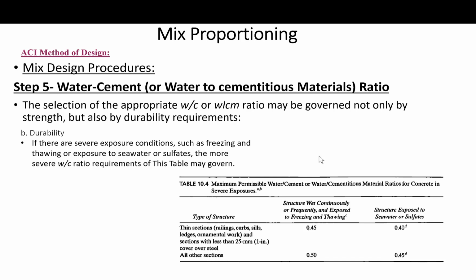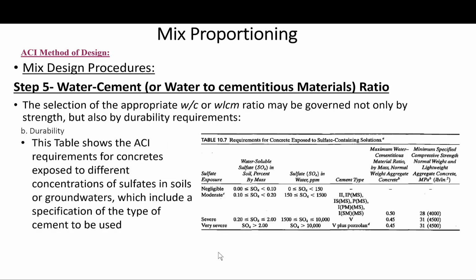Maybe, for example, the Canadian standards will also call for different requirements. It has actually a more detailed guide to the selection of the maximum permissible water cement ratio and concrete strength and so forth. What I'm presenting here is purely what's followed in North America based on ACI.